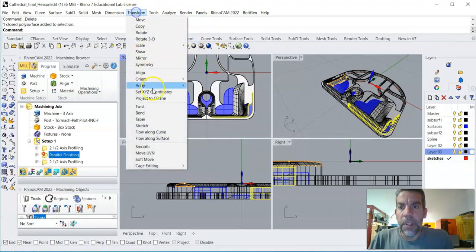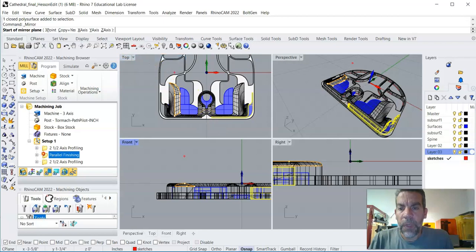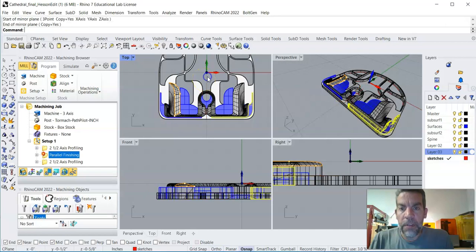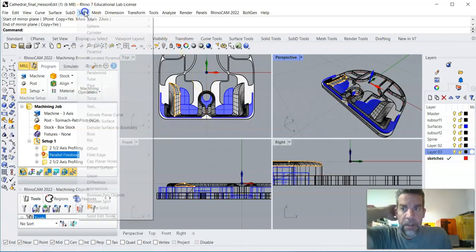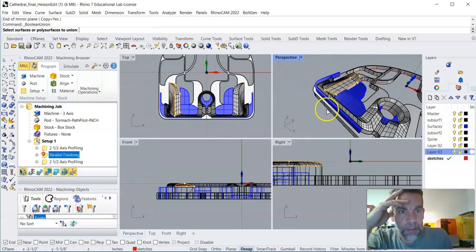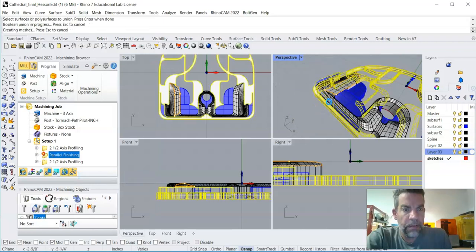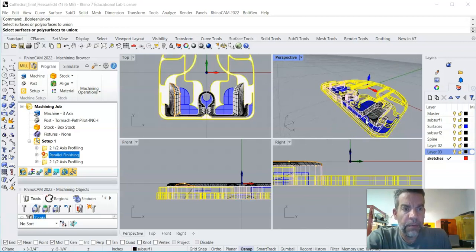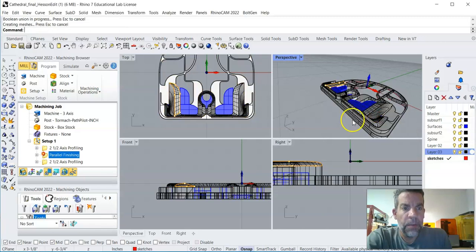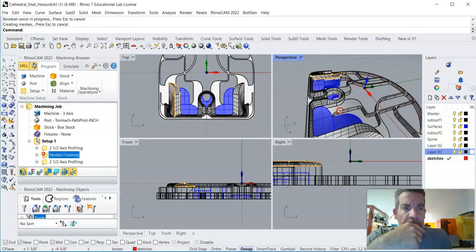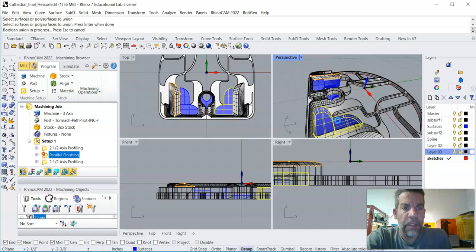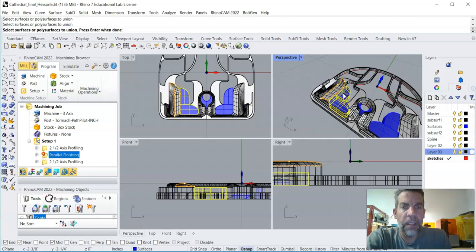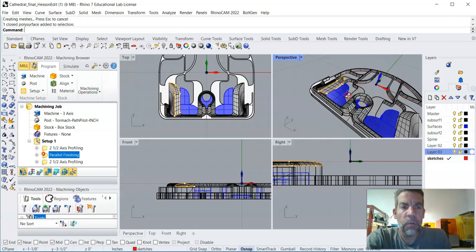So transform, mirror. Let's turn on midpoint. Hold shift. Okay, let's try a union on that. Solid union. Sorry, we're running into some modeling stuff here. Yeah, see that unioned fine. So there was something bad with that surface, or with that poly surface. And then we can union that. So now those are joined. Typically we would union this and this. Yeah, see that? It was fine there. And this and this. Okay, so that's one surface now.